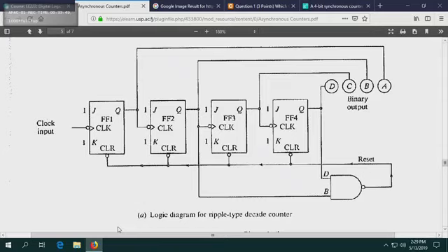So we were able to get out of it very easily using a simple NAND gate. But you have to be careful. Sometimes a simple NAND gate won't work, depending on the scenario. Over here, we only use 2 of the inputs. Some people would use sum of products. Let me give you a chance to discuss. Let's say the maximum count was 9, 1, 0, 0, 1. After 1, 0, 0, 1, it's going to clear back to 0. If you used sum of products, what would you do?